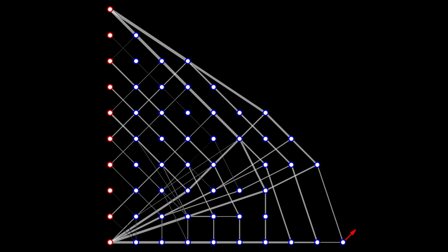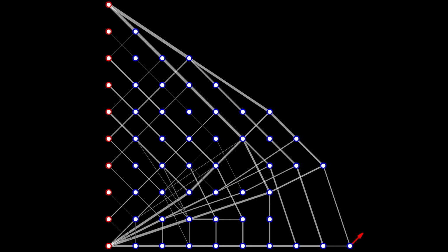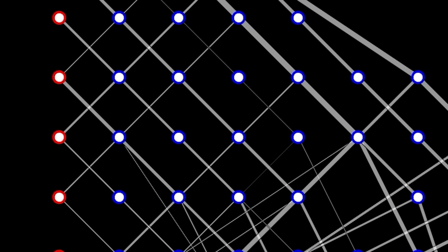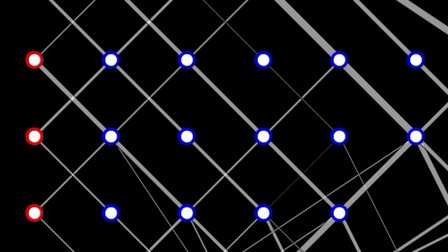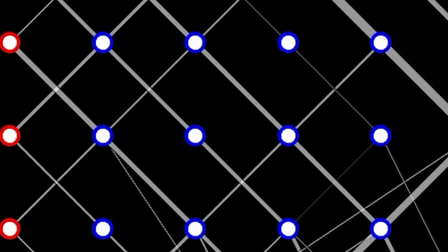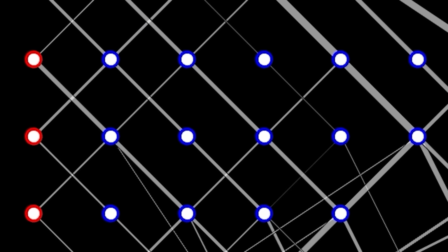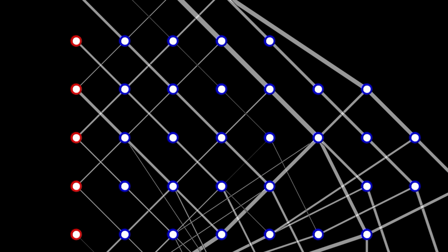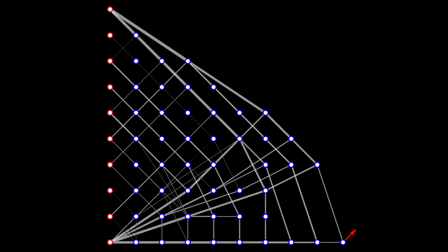And if you look closely, you will also notice that there are nodes in this truss that do not appear well fixed at all. And in general, you will have to find a compromise to obtain a robust solution. Because the more you distribute the given material on bars connected to nodes on which the considered force F probably won't be applied in practice, the more the truss will deform if the force F actually works on the truss, because you will simply move away from the best solution for the force F for this truss.